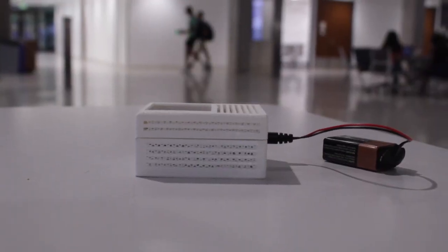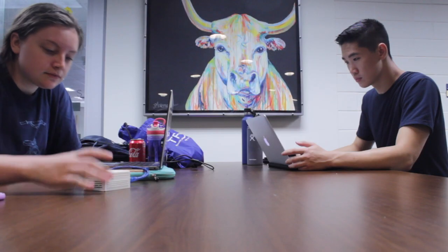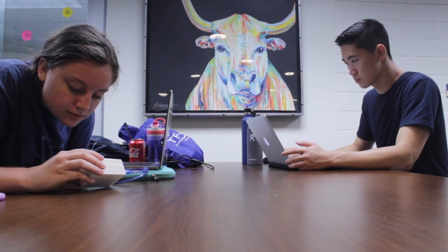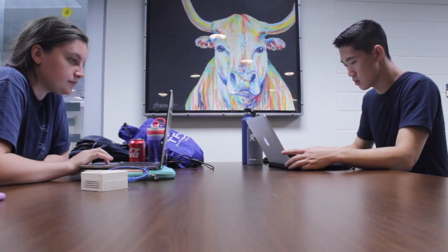Another main challenge was the SD card not properly collecting data from the Arduino board. We fixed this issue by collecting data directly into the computer instead. This is not ideal since it made the sensor dependent on the computer and made it a lot less portable.